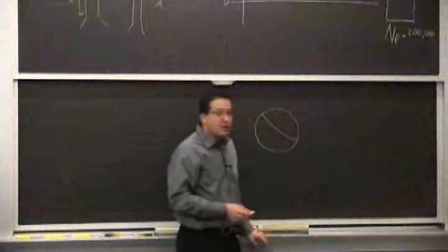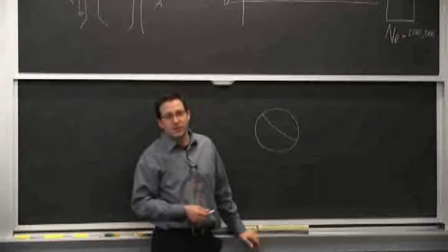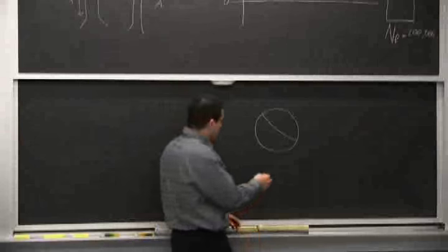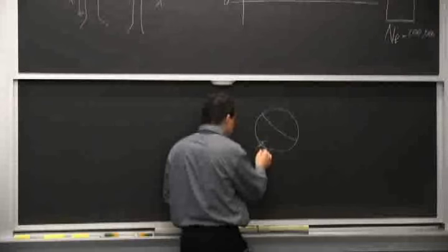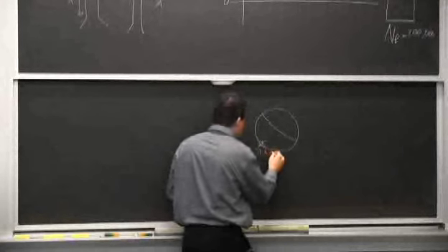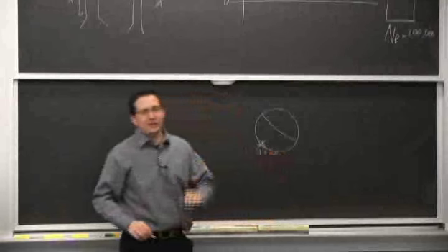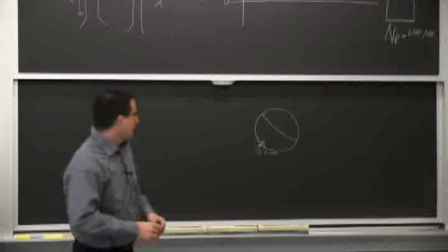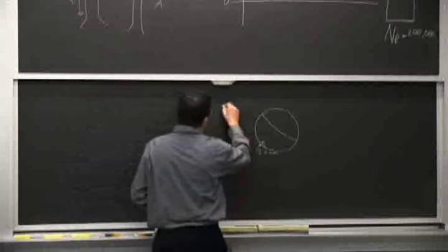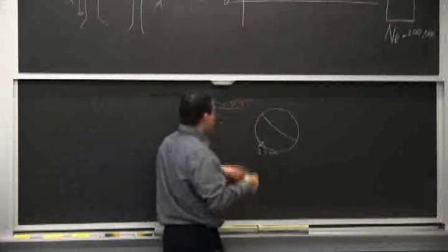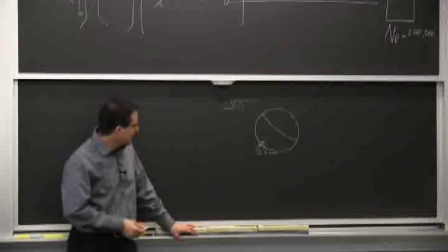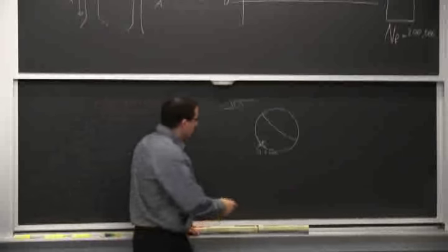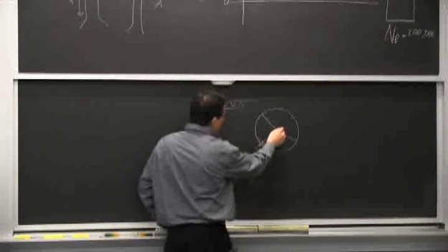One way we can do it is say, hey, you know what? I think I have a crack already to begin with. Day one, I start with a crack here that would be 0.2 millimeter. So it's visible. In reality, you don't have it, but we'll just say we have it. And now we know our bending load, depending on RPM and everything. We have a good estimate for that. So the way we will evaluate that design is to say, okay, what will be my number of cycles to go from here to there?